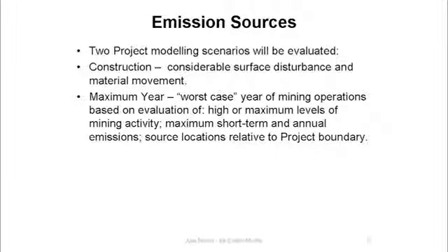Two emission scenarios are going to be evaluated. One is during the construction phase, where there'll be considerable surface disturbance and material movement, and one during the maximum year, and that'll be defined in the mine plan as the worst case year for mining operations based on the evaluation of maximum levels of emissions, of mining activity, of source locations relative to the project boundary. That is a specific answer, and it depends on the mine plan, which is once that's defined, then the analysis goes into choosing what the maximum year is going to be, and that's what will be evaluated.